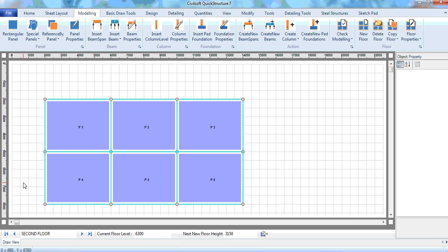Okay, this is exactly the same thing with what we did earlier, but in this case we're just going floor after the other. This approach is very good, assuming your floors, you have the GAs, are all different, although as I said, you can achieve the same thing by copying multiple floors, later editing each of the floors however you want them to be. But for instance, I just want to show you a different approach that you can use to achieve the same thing. Okay, so now the next thing again, I can now copy the roof level.